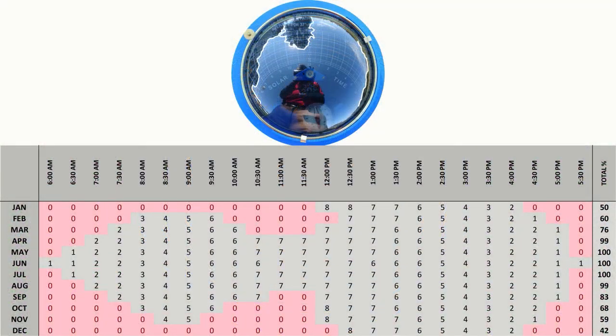For a more thorough assessment, you may want to enter this information on a spreadsheet. In this case, I've entered the percent of radiation for each half hour for each month. The totals are calculated in the software, and we can see that we have access to less than 75% of the potential radiation in the winter months due to shading.